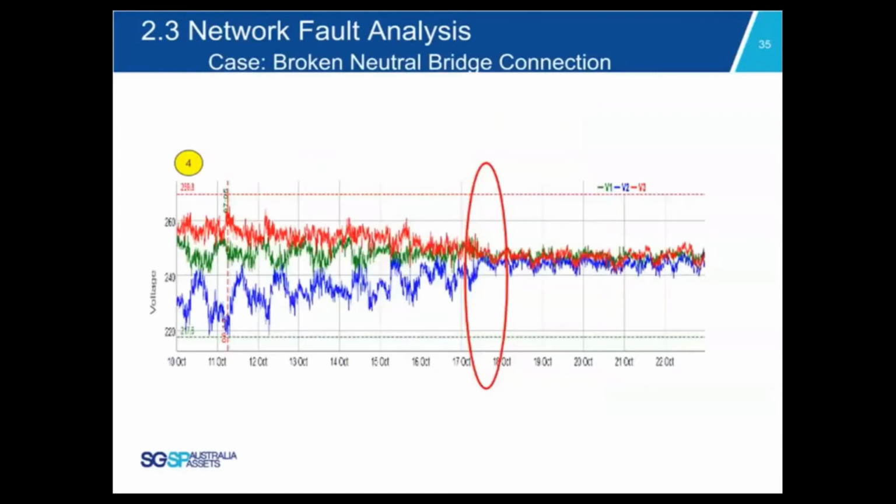After the field crew fixed the neutral bridge connection issue, the operator needs to make sure all the faults have been addressed. Based on the three-phase voltage pattern before and after the repair, this fault case can be closed.